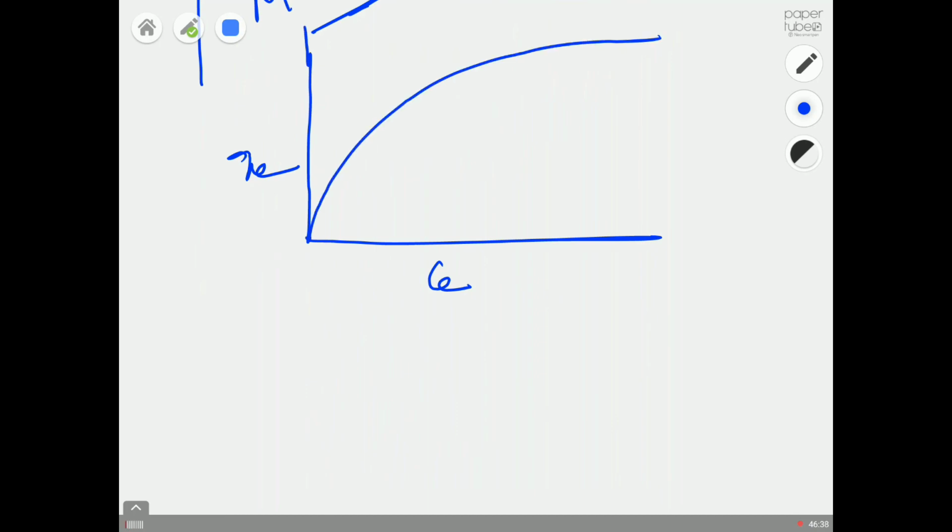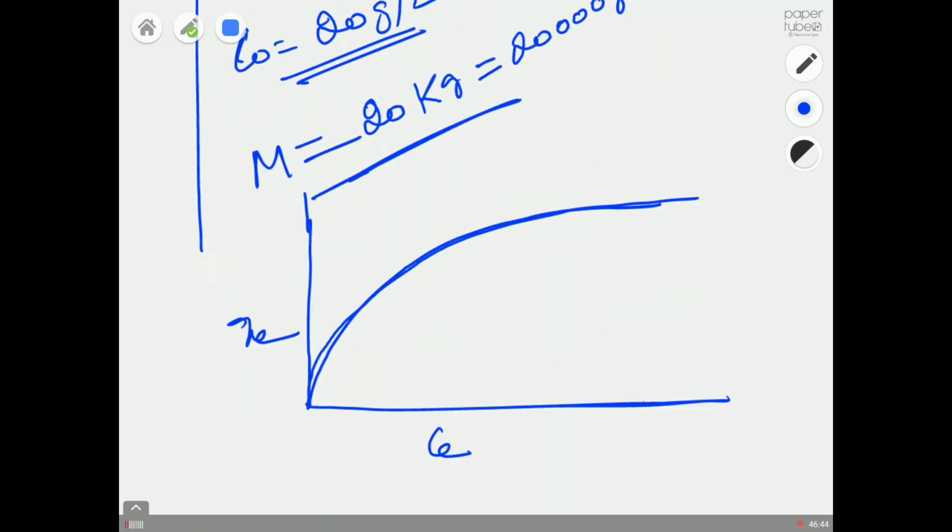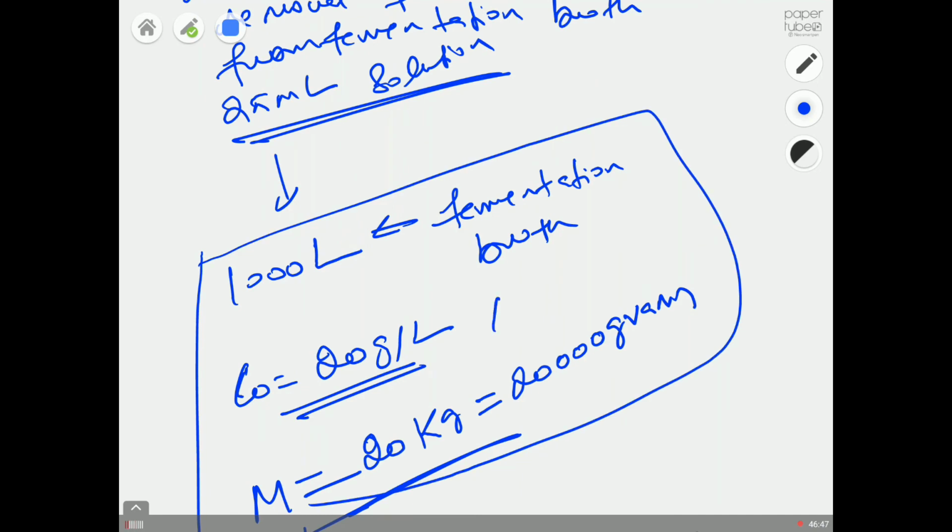And if I ask you, and you have the equilibrium data CE versus QE, which is obtained just with the 25 ml reactor, but you have a very beautiful curve CE versus QE, and if I ask you to calculate what the CE will be in the industrial scale reactor, you can get that value without performing an experiment in a large scale reactor.